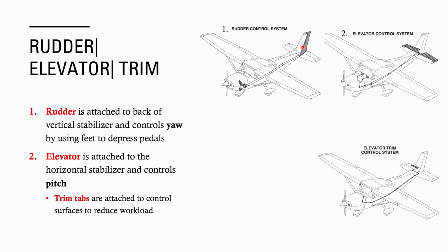We don't say, oh, I need to turn right, let me add right rudder and go that way. It assists your ailerons in performing a controlled and coordinated turn. Generally, if you turn right, like we mentioned last time, you're going to have adverse yaw, which brings this wing back like that. So now the tail is to the inside of the turn, which is performing a slip. In order for the tail to align with the nose throughout a turn, you add right rudder, and it keeps these aligned and coordinated throughout a turn.